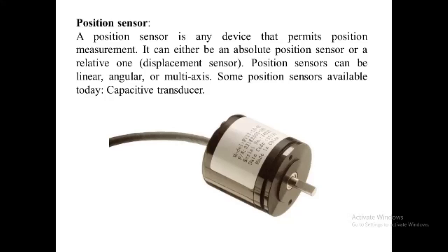Then, for example, if you apply a voltage of say 10 volts across the resistive element of a potentiometer, the maximum output voltage would be equal to the supply voltage at 10 volts, with the minimum output voltage equal to 0 volt. Then the potentiometer wiper will vary the output signal from 0 to 10 volts, with 5 volts indicating that the wiper or slider is at its halfway or center position.